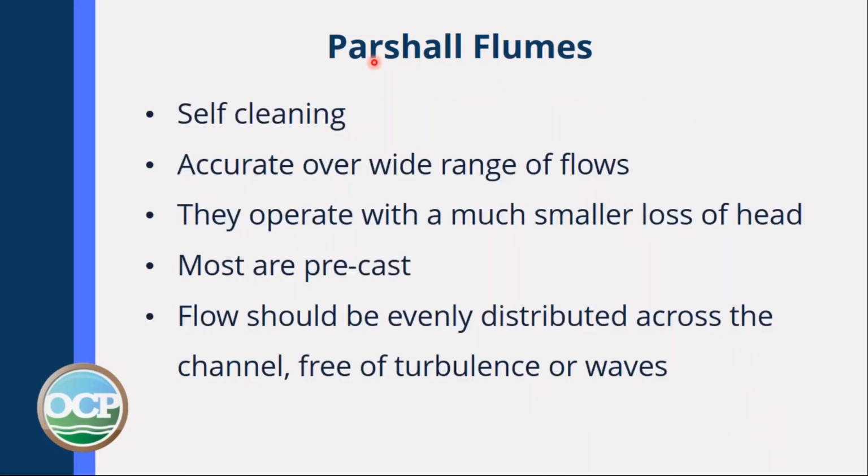So, what are the advantages of partial flumes? I mentioned earlier that because of the high velocity, they tend to be self-cleaning. They have the advantage of being accurate over a wider range of flows than weirs because they are not flowing over something.